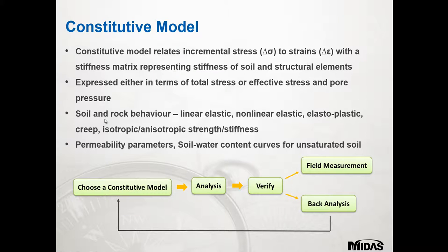So the soil and rock behaviour can be linear elastic, non-linear elastic, or elastoplastic, creep, isotropic and anisotropic, and also the strength and the stiffness, which is modelled within the program. Permeability parameters, which are the soil water content curves for the unsaturated soil, are all related to the constitutive models within the program.